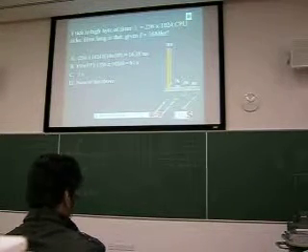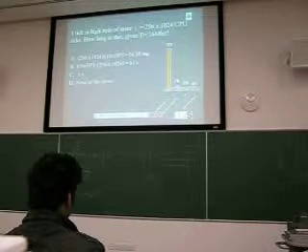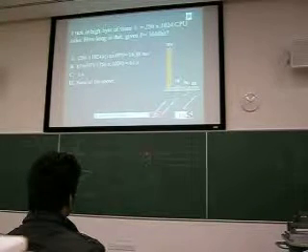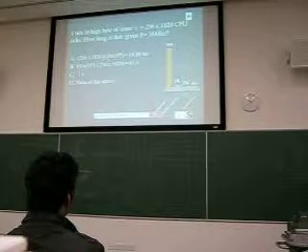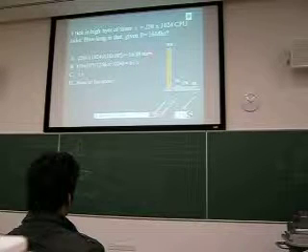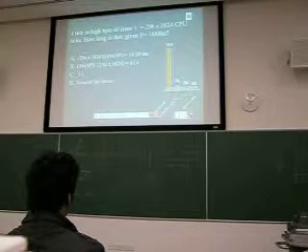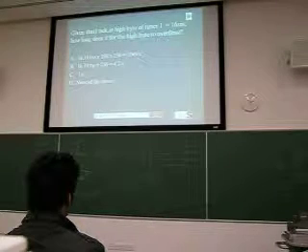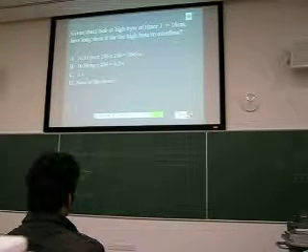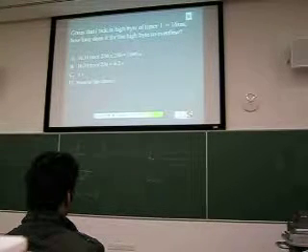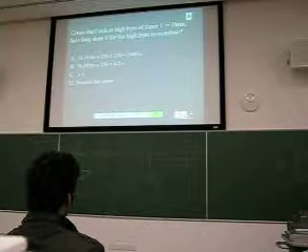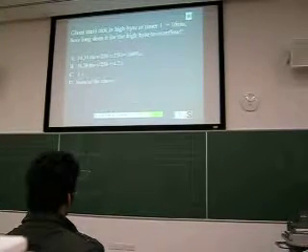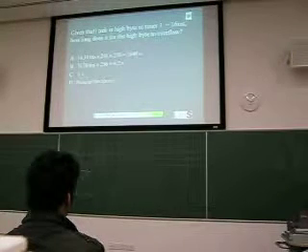Okay, so it's 16 milliseconds. So 1 tick in the high byte corresponds to 16 milliseconds, roughly speaking. Now, let's look at this one, which is similar. We want this one to overflow. Overflowing means it counts from 0 up until every bit is 1.